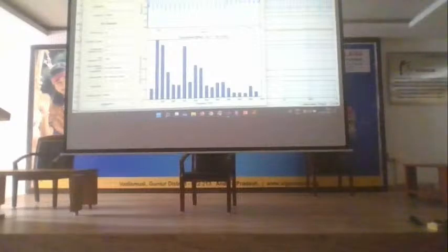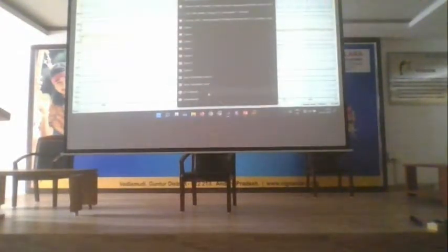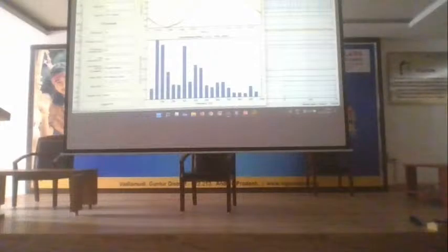See that the THD is like 2.69, it's less than 5%. What we actually need is less than 5%, so we achieved it, and that is the beauty of our design. This is what we have seen here, right? So this is the waveform that we have analyzed, the quality of the current which we have. We have achieved unity power factor and we are achieving 2 point something THD. This should be less than 5. We are at 2.6, so we achieved it.